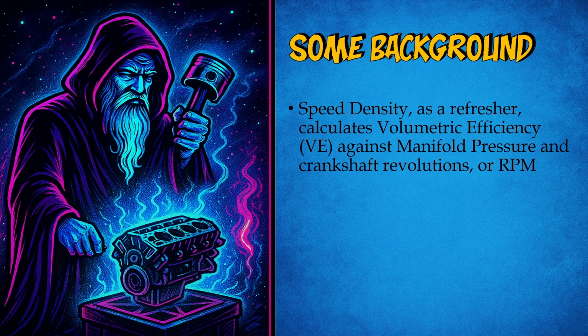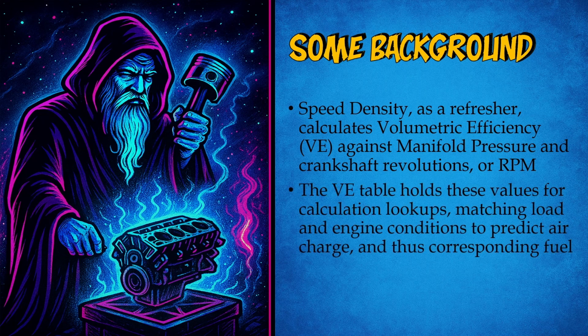I know that I have air coming and going under load. I know that if I plot each of these points, right, I can have a lookup of a number that is essentially a percentage. For this load and for this RPM in this pocket, you're going to have a value of 0.58, which is going to be 58% of the total maximum air load possible, right?